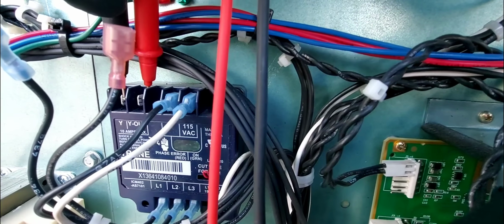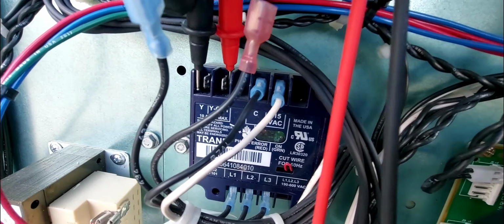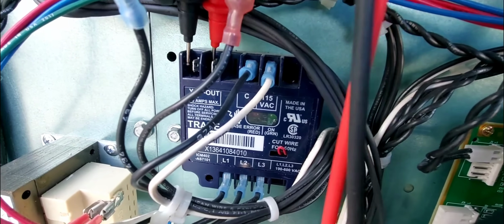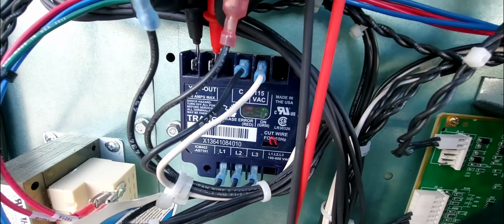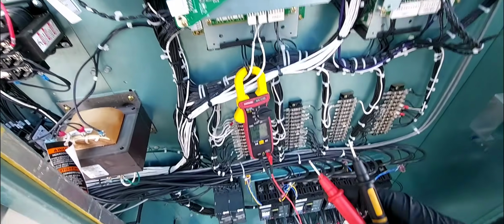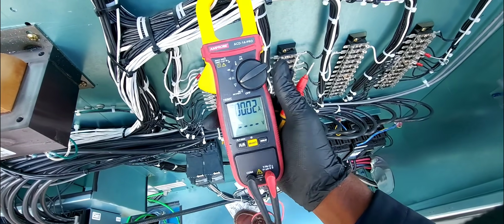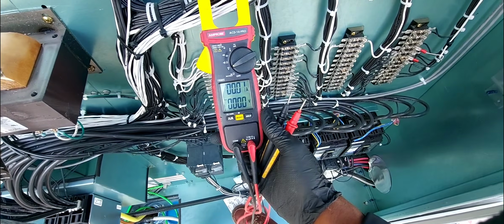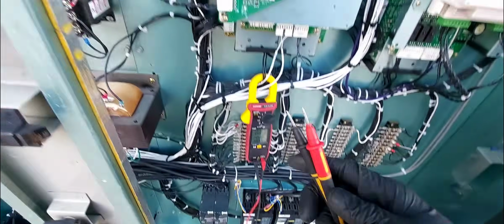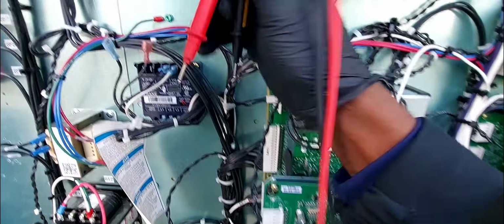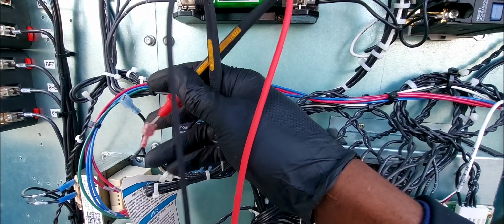It's not ringing out, which means that this is open. Nothing. Come on, let's test the lead. Yeah, so that's open. Which means that, let me go into DC. So the phase monitor is open, so that's the culprit, 99%. All right, so be aware of that, guys. If you pull up to these units and you see external stops, you might want to check your phase monitor as well.